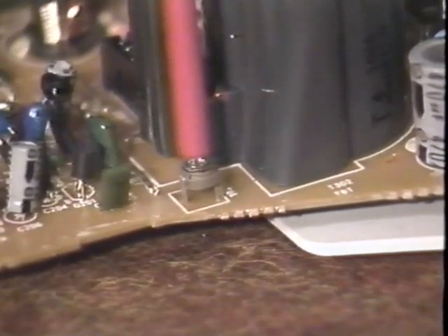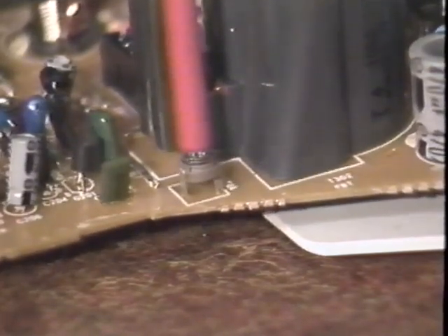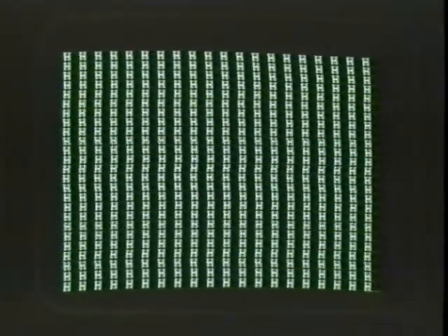Adjust the internal horizontal sync control until the display is stable and the edges of the display are straight. Next, adjust the horizontal width control until the display area's horizontal measurement matches that described in the manual. If the unit you are servicing has a horizontal linearity control, use it to make sure that the characters remain the same width across the screen. A full screen of capital H's is a good pattern to check this with.